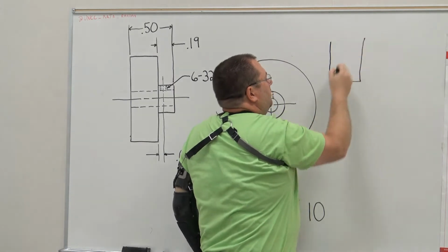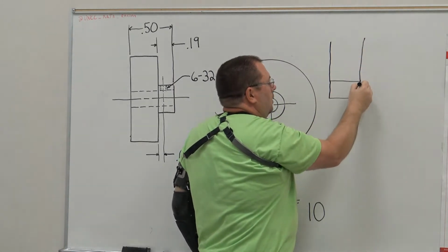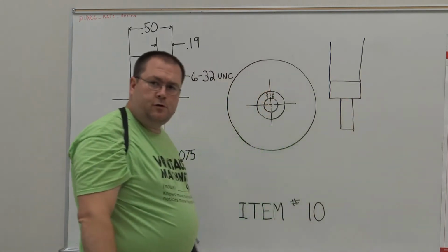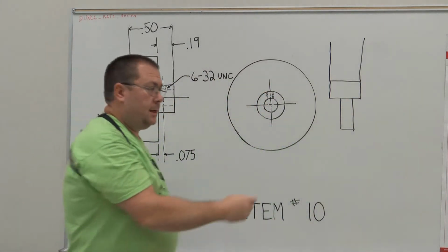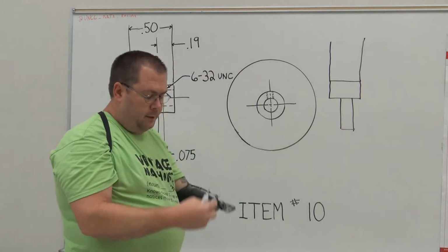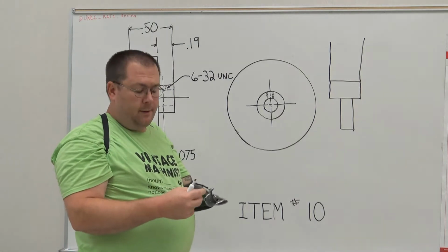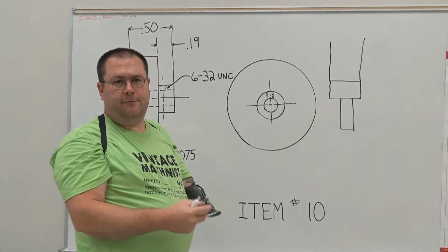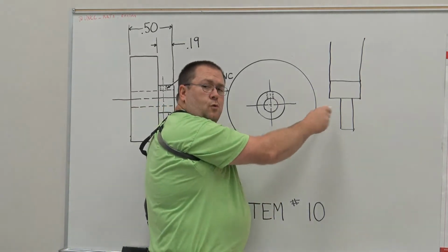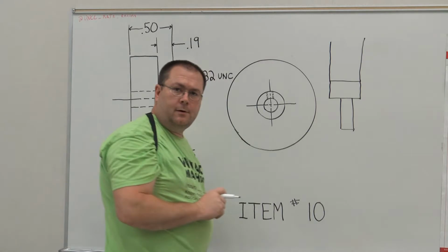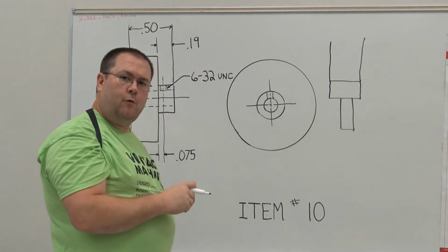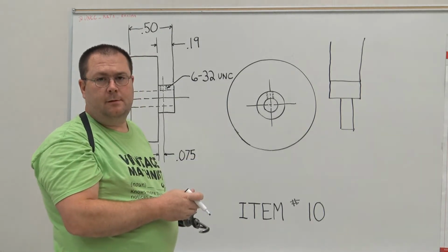But we do have a component or a tool that we've used previous to now. This is cylindrical, and you should know that this cylindrical component is held together by a spring, and those two ground and lapped surfaces allow it to run out of concentric. This tool is called an edge finder. You should remember what that is, okay? Remember the name for it and how it's used.